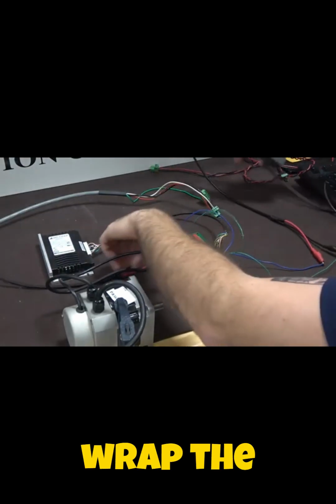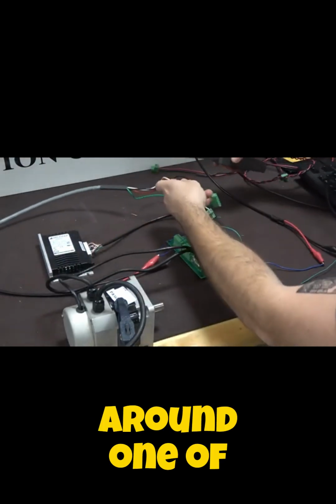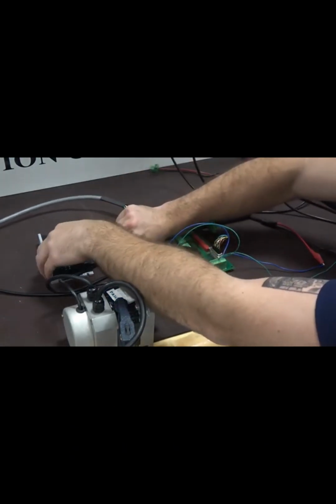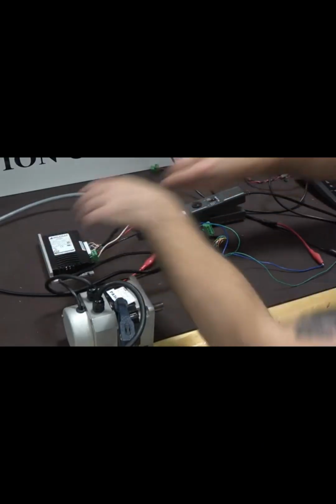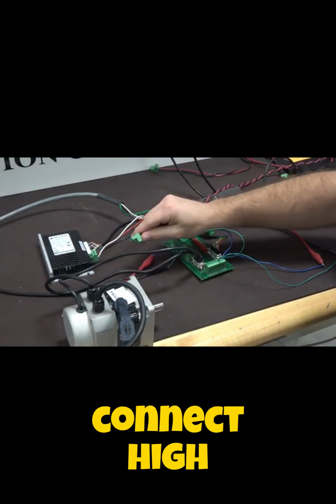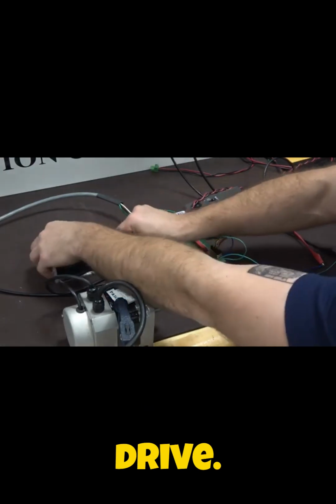We will then wrap the current probe around one of the motor leads that will be connected to the drive. Then connect the motor leads. Finally, we connect high voltage and ground to the drive.